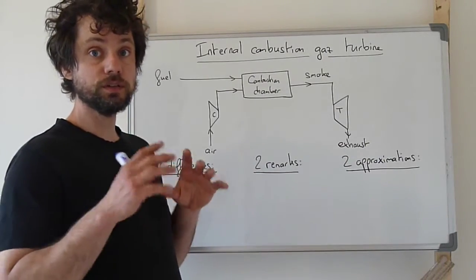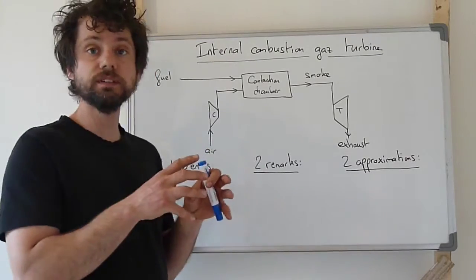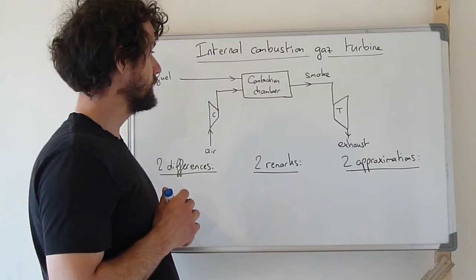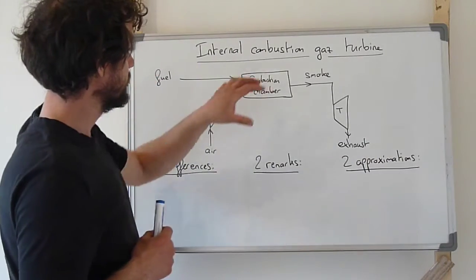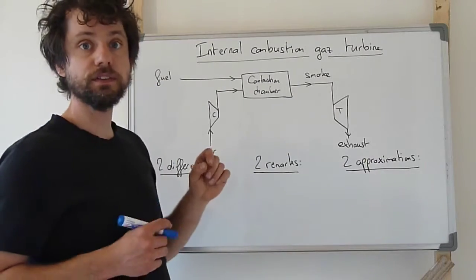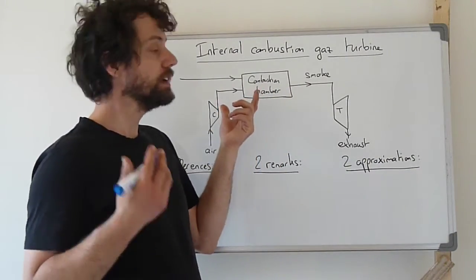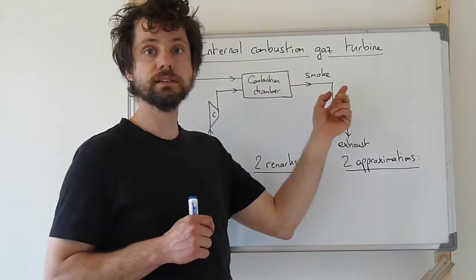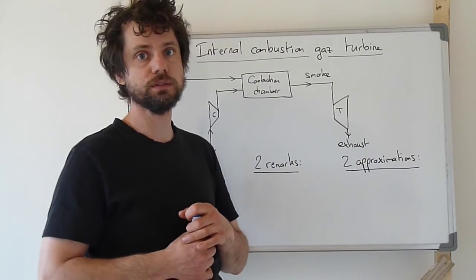internal combustion, it means that inside the working fluid that is following the different transformations in the system, there will be combustion, and this combustion will directly increase the temperature of the high pressure gas instead of having a heat exchange in a heat exchanger with a hot source.